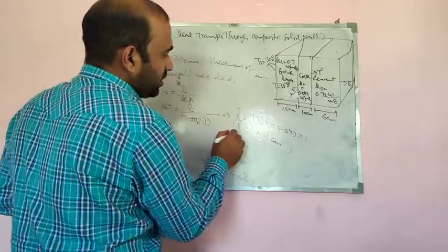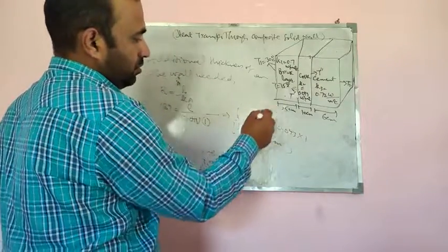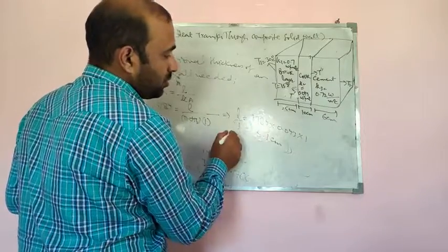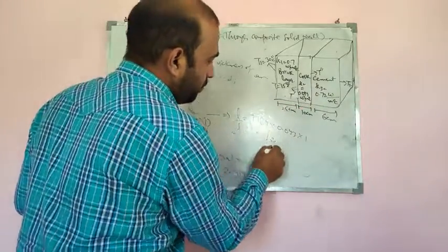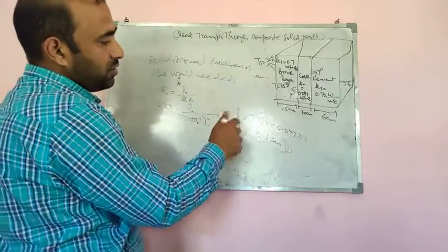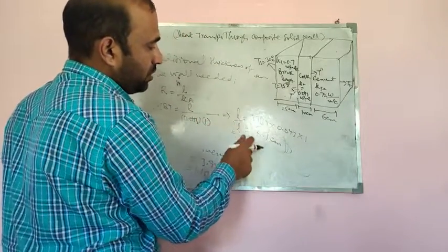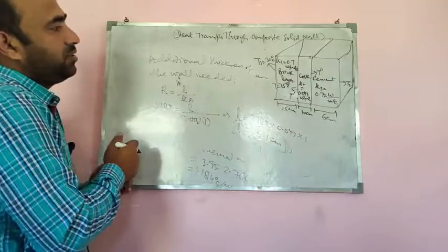So basically this additional thickness of the cork has to be introduced. The thickness of the cork is 10 centimeters, so you have to add 5.1 centimeter more, so that the desired rate of heat flow through this wall is 30% less than the present value.